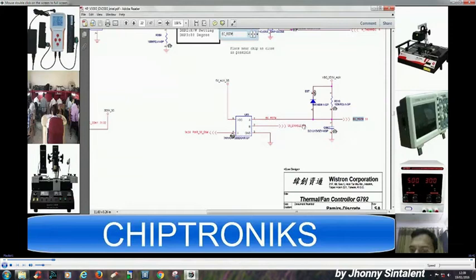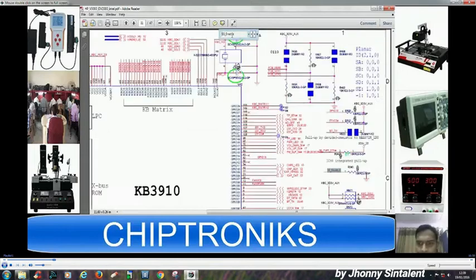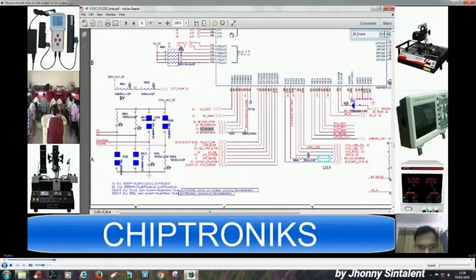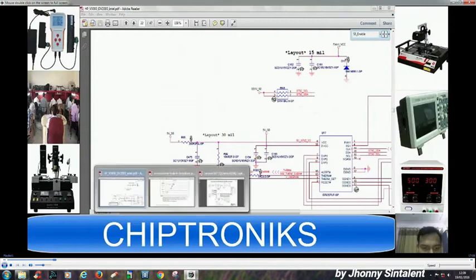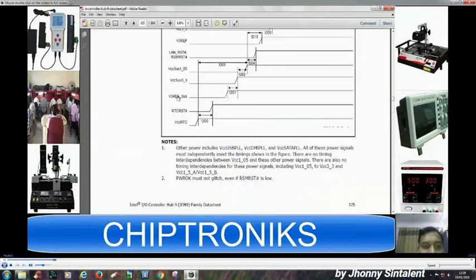And this S5 underscore enable will come from the IO controller, right? We have to just see S5 underscore enable. So that means this signal V5 ref underscore sus will get generated only when this is present.